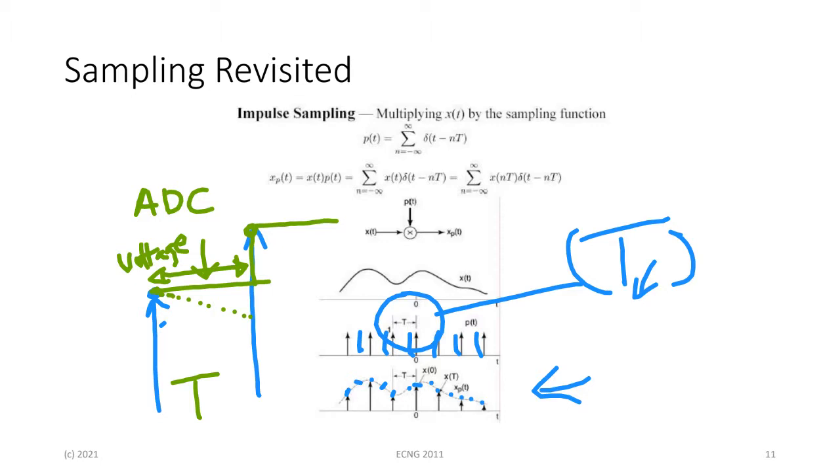If the value happens to be changing along a line, if it is discharging, then if the computer checks it here, certainly that is wrong. There's a difference between what the correct value is and what the measured value is. So all of that is part of the whole process, and we're going to talk about, well, not here, but if you're doing the electronics course, we will talk a little bit about ADC and those designs to mitigate that kind of behavior.